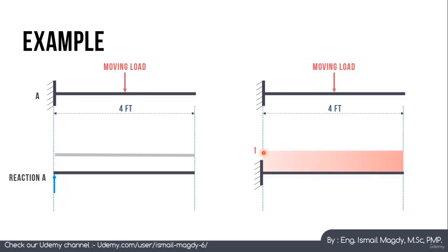And this actually makes sense because this is the only vertical support here we have in this system. So wherever you put the moving load, the vertical reaction, it will always be the same. If you have a 4 kilonewton vertical force, it doesn't matter at any point you put it, you will keep having a 4 kilonewton upward force here. The only difference will be in the moment, but the vertical force, it will always be the same as the case of the cantilever.